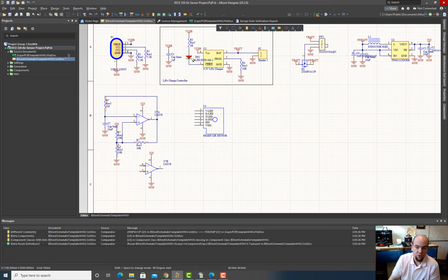And this is a really simple, really cool circuit that you can use anytime you need a pulse train. There's a formal version of this called a 555 timer. People might be familiar with it, where basically it's effectively this circuit, but there's all sorts of other neat things you can do with it. But at its core, it's doing this: it's using RC charge and discharge with a circuit that shifts the voltage set points required to reach equilibrium across the input terminals, and that allows it to create this astable operation.